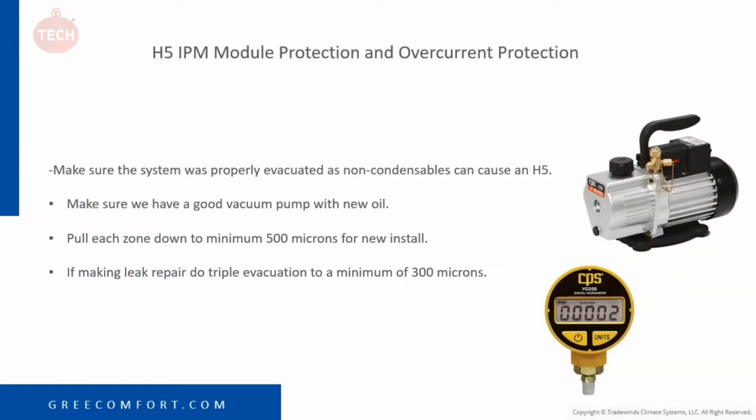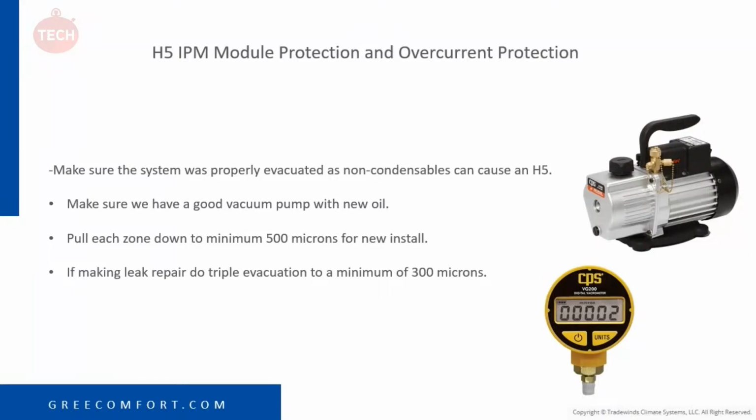We also want to make sure that the system is properly evacuated, as non-condensables can cause an H5. So we want to make sure we have a good vacuum pump with new oil. I had a coworker who would only change his oil when it spilled all over the back of his van. So that's how I knew he got some new oil in his pump. So again, this should be done after every install. It is highly recommended to put new oil in there after each install. At least do it weekly. Just don't be my coworker that did it every few months when it spilled all over his van.